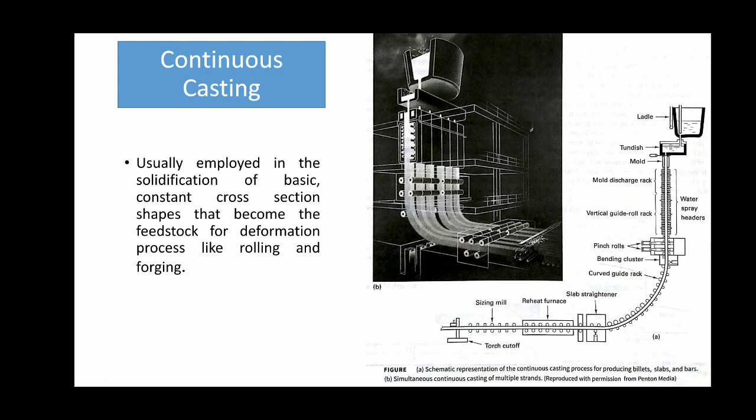We also have, in the process industries, continuous casting. So what is this continuous casting? That means continuously from the molten metal itself to the final shape of the cast part that is required, step by step, in the long run the whole process is completed. That kind of casting is generally known as continuous casting. The feed bar stocks, billets, blooms, etc., of mild steel, cast iron, etc., are generally made in the industries by continuous casting processes.